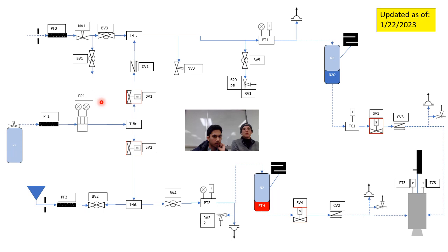There's a lot of good things that come out of pressurizing before we fill. So we slowly increase that pressure regulator. I don't know how slowly, but we don't want to just crank it. We increase it to 820 PSI, maybe more given the temperature of the day.